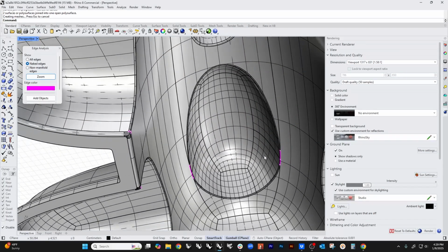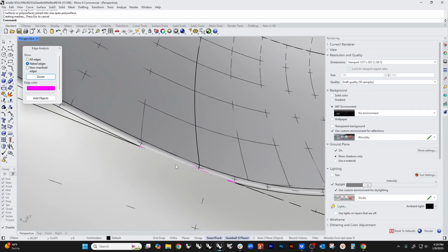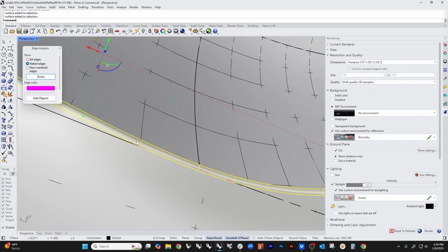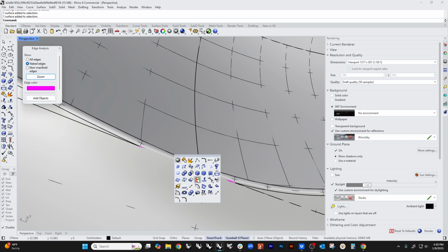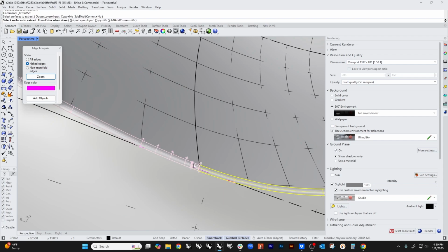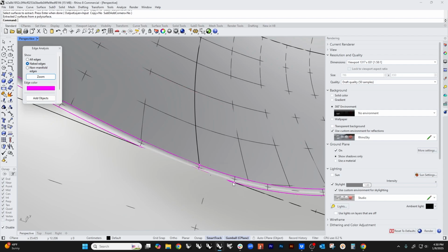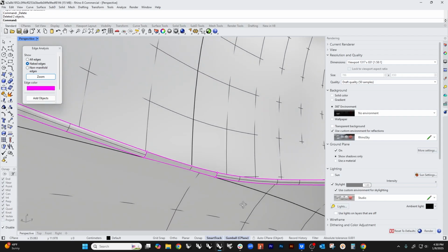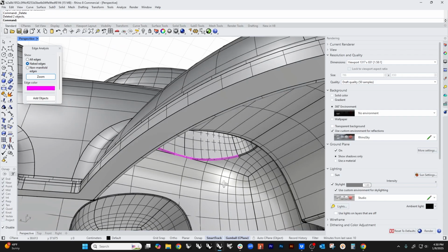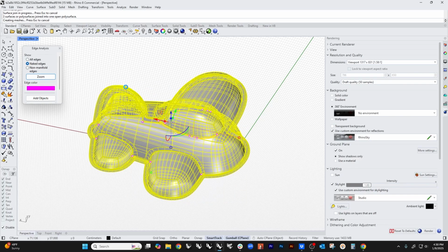And this one is interesting because the blend didn't cut this surface here. So same problem, same thing we're going to do on the outside. I'm going to extract this. And I can do one of two things. I can either trim this out, if that blend is super important, or same thing I did before. Split by isocurve, hit the toggle key, T enter, snap there, split this one, get rid of this, and it pinches a little bit, but I don't really care. It's on the inside, and it's tiny, and no one cares.